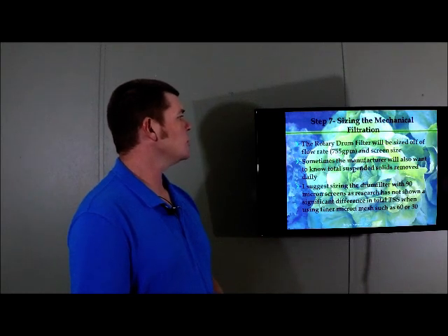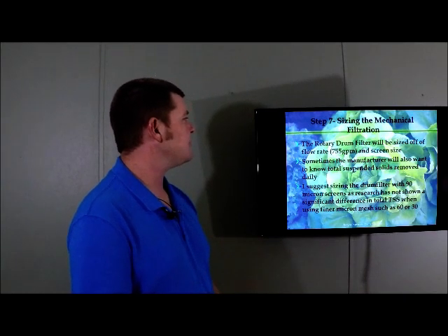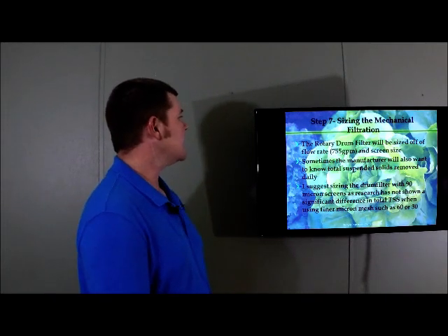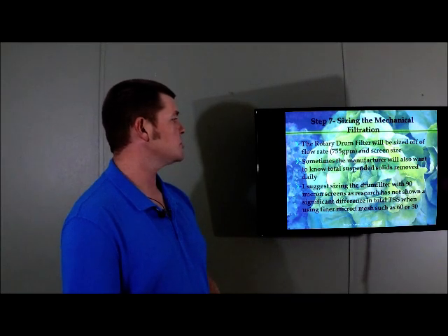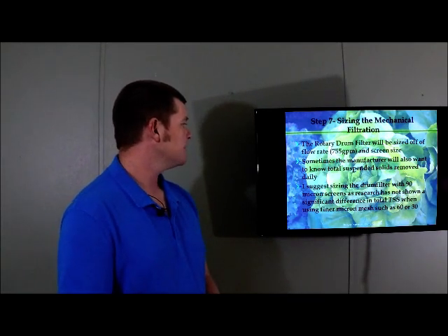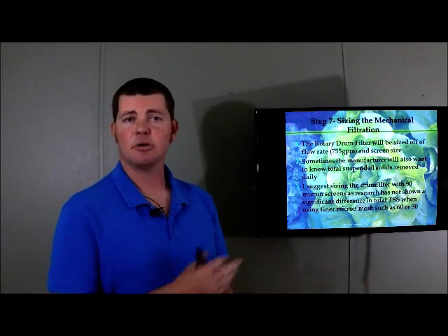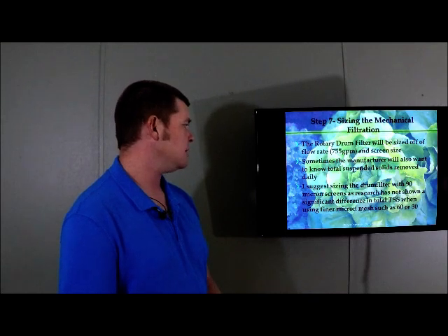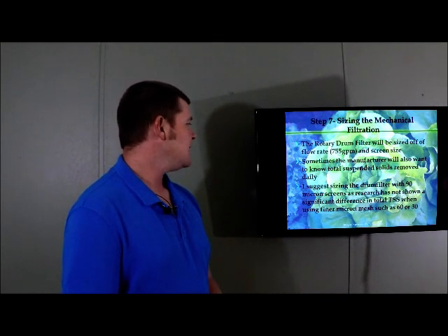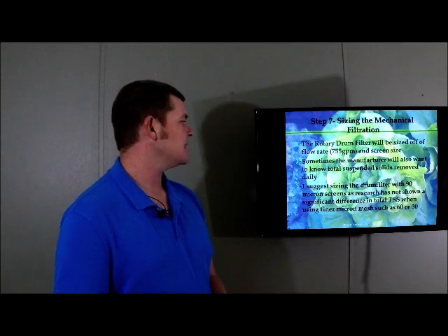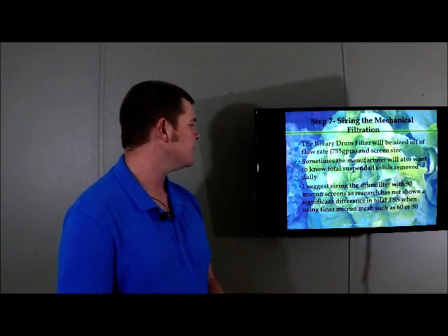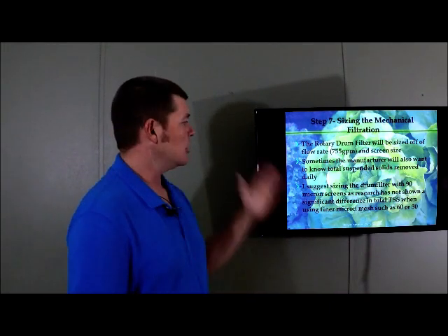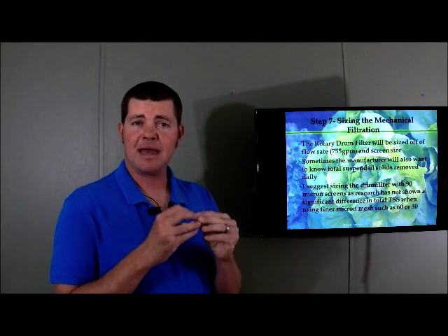The rotary drum filter will be sized off of the flow rate, 755 gallons per minute, and the screen size that you choose to use. Sometimes the manufacturer will also want to know total suspended solids removed daily, okay, which we can calculate off of our total feed input. I suggest sizing the drum filter with a 90 micron screen, as research has not shown a significant difference in the total suspended solids removed when using finer micron mesh such as 60 or 30 micron. So the lower the micron number, the finer the mesh.